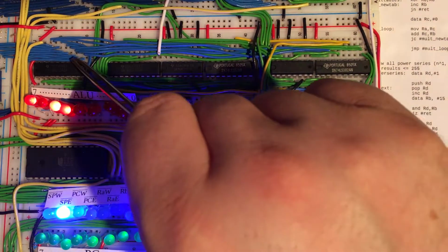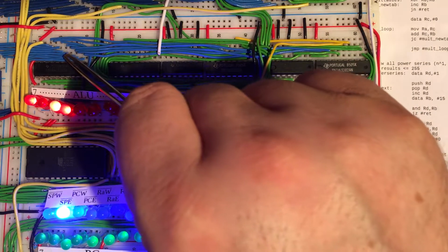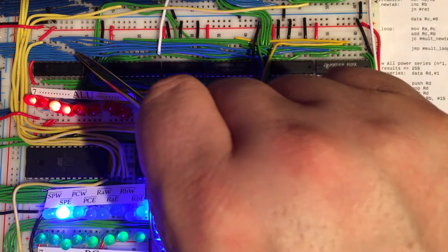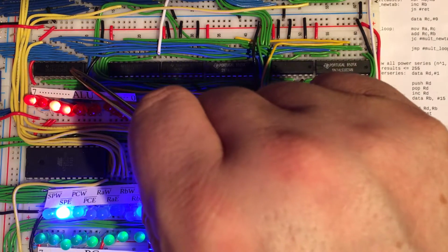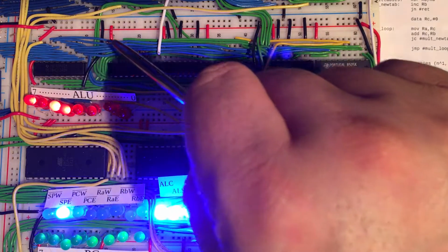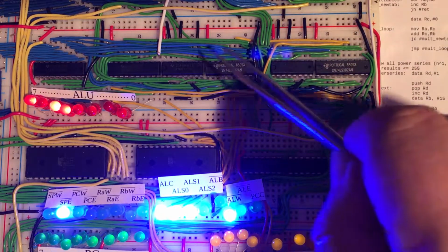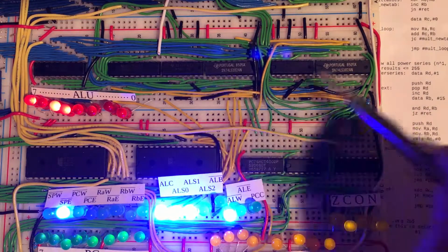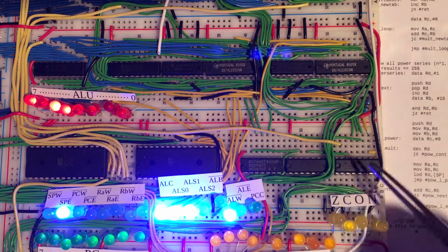And the input to the ALU, of course the first input also comes from the bus, and so these blue wires, which represent the bus, which this buffer sometimes outputs to, are also connected to, and we'll see later how that works, all of the inputs of the real ALU, and the ALU is split over a number of chips, over here and over here.